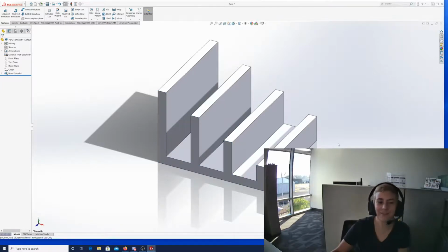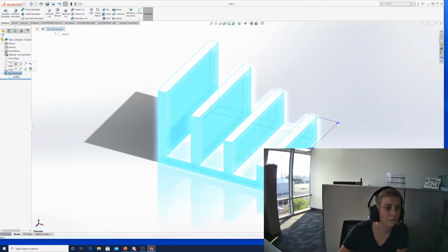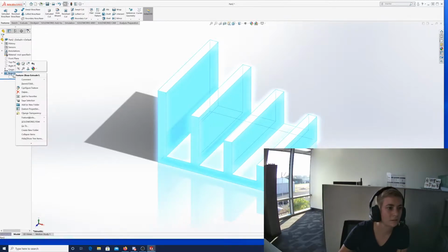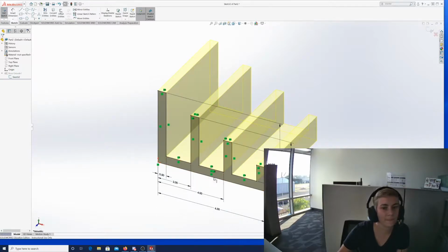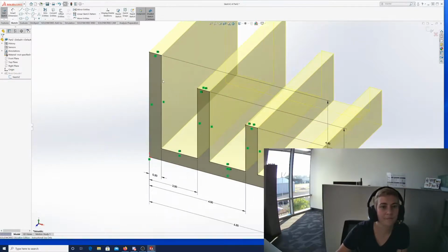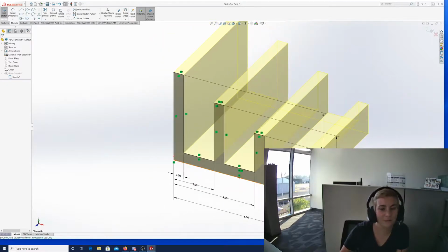It might be the dimensions. You might have used different units. So when you extruded it, did you just put in 6? Oh, okay. And it's just getting way too long as you're adding in the measurements.